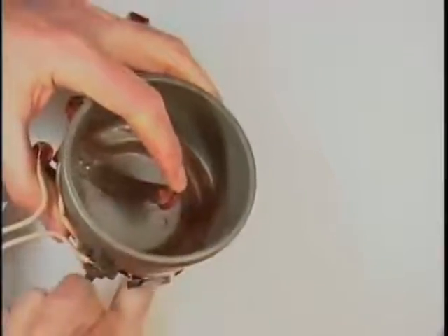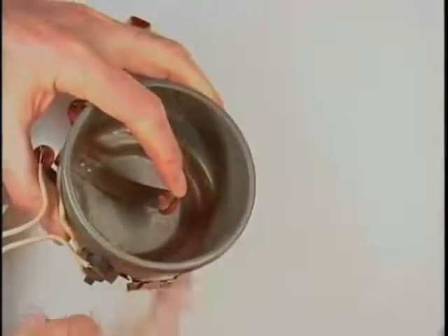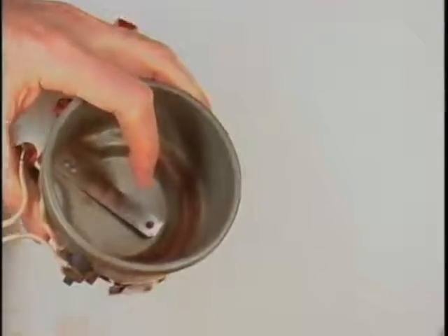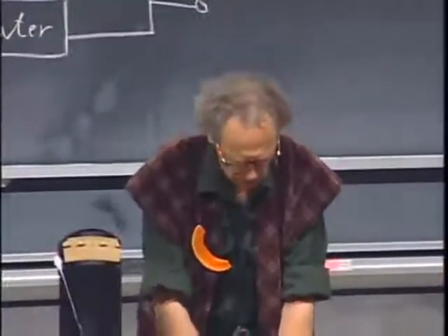there is a hole there. This is the hole. And the water comes out, and when the bimetal is closed, then it closes off that hole. So it's an amazing, simple idea. The criterion for letting the water go through the coffee is simply when the water reaches that temperature, close to boiling, and you have your bimetal control it.